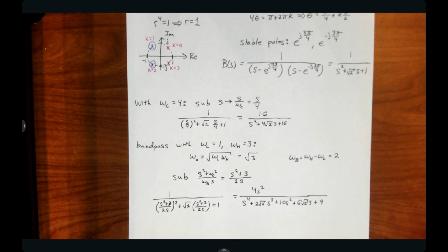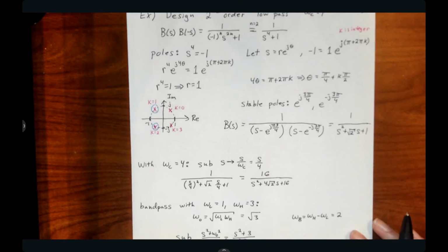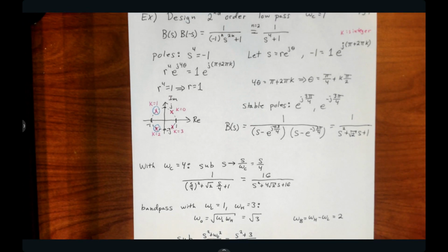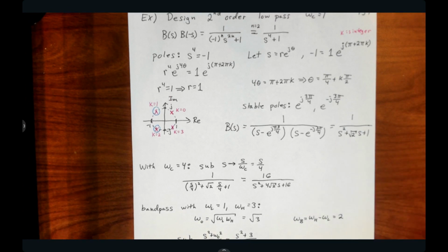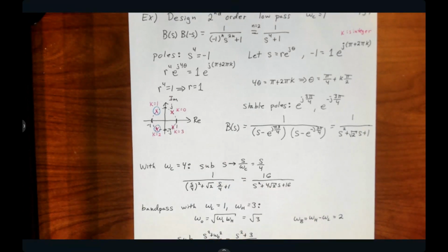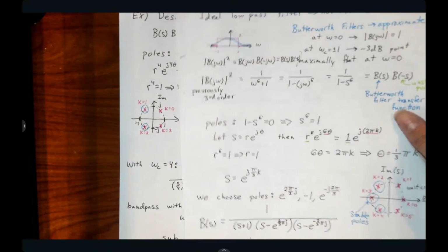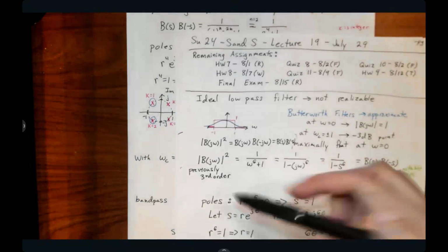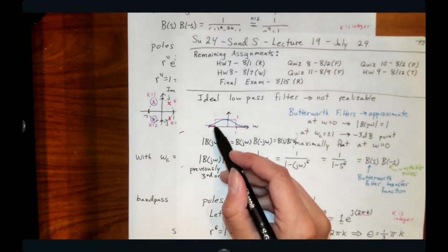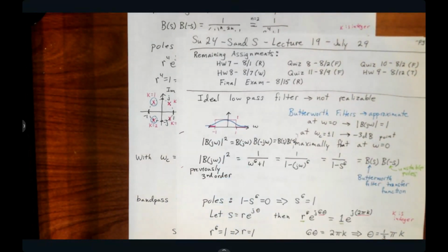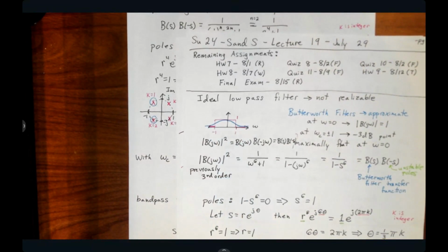Another thing that you'll notice is if you look at the response magnitude as you increase the filter order, right? So if you compare the second order, say, to this third order that we looked at back here, if you look at the frequency response, what you would find is that this edge here is going to become sharper as you increase the order number, right?